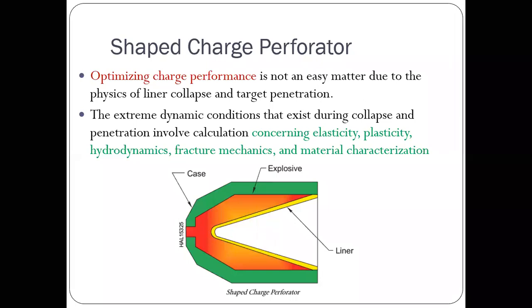The important parameters are the formation type, what kind of permeability the formation is having, what is the mechanical strength, whether it is a brittle structure of formation, and an important one is the shape of the liner, and what kind of charges we are using. They are going to affect the perforation.